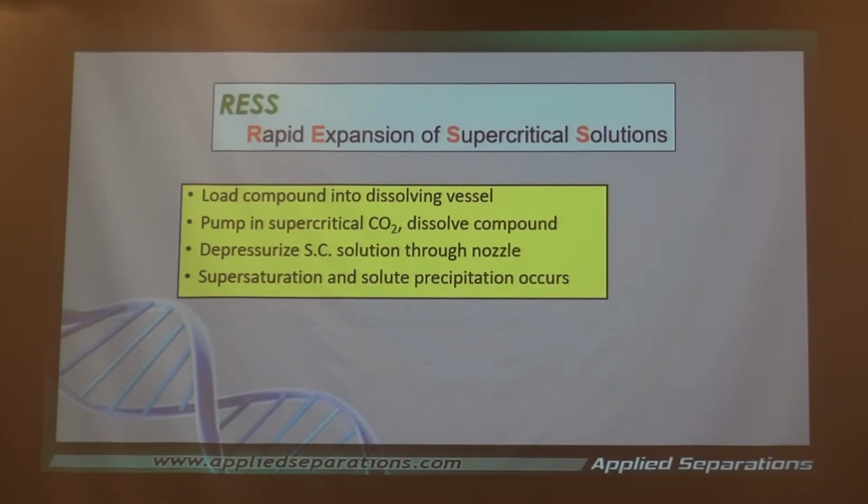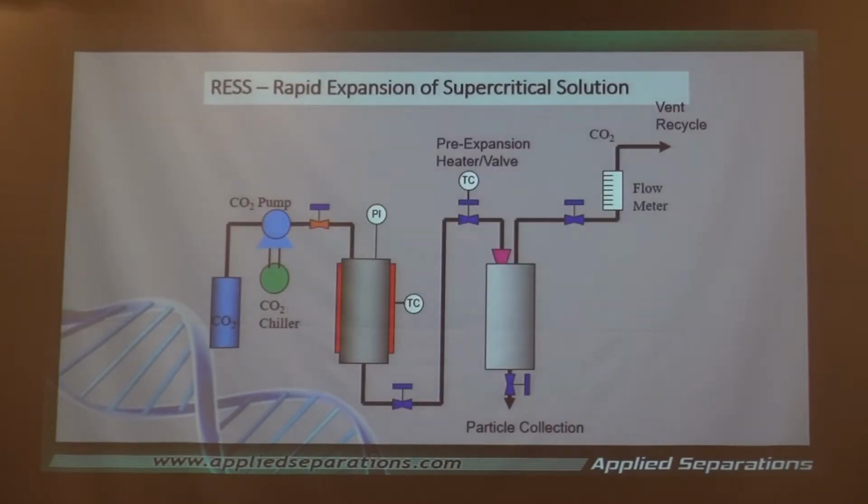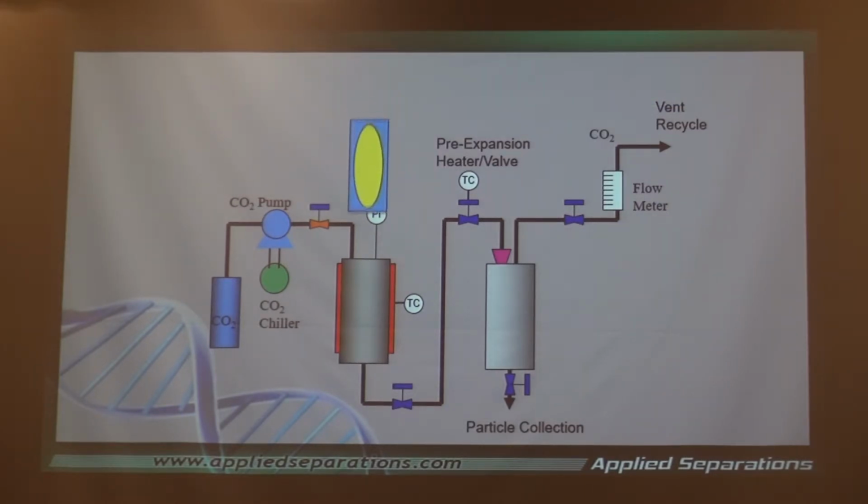We load the compound, we pump in the CO2 to dissolve it, and then we depressurize through a nozzle. And then this supersaturation occurs, and the solute then becomes particles. Let's look at it this way, through the diagram here. Here's what happens. We load up our compound.